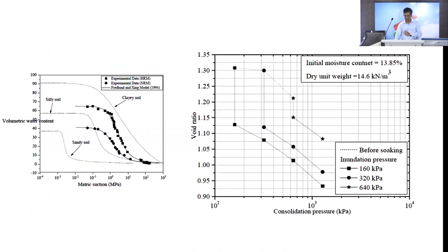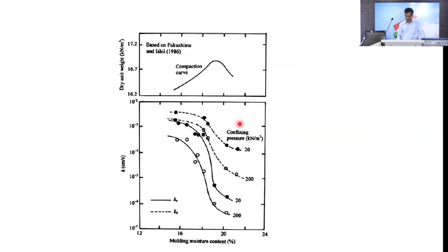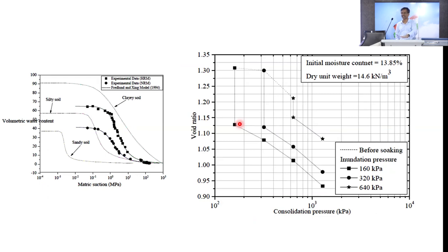Suppose the void ratio is 1.3 in one case, and suddenly if I make it wet, it reduces to 1.15. With the same moisture, I was compacting, then I put some dry, then left a little water, and it settles immediately. That also happens in many tailings: we think it is already compacted, but it is not really compacted, and once it saturates, it gets compacted again if you add water. I will not complicate this, but that's why people working on tailings are talking about unsaturated soil mechanics.